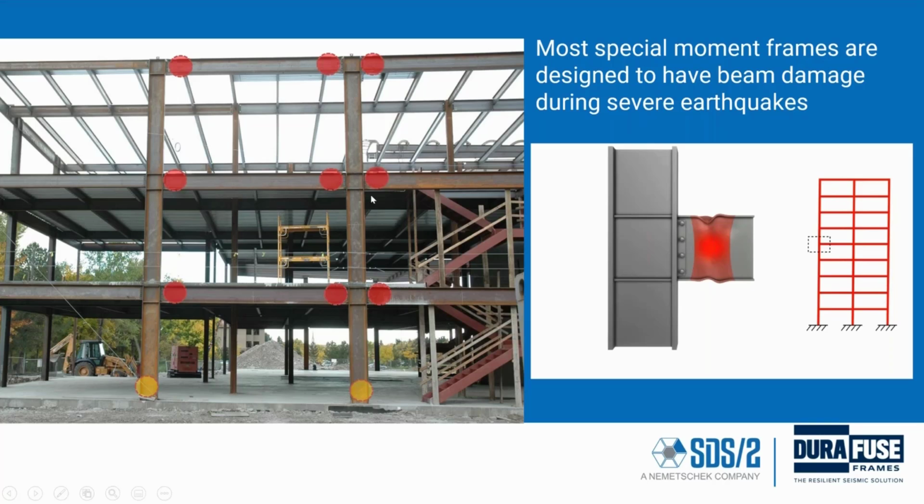Here's an example of a moment frame building. And when I say moment frame, I'm talking about frames that don't have braces in them. Here's an example moment frame, and these red zones are the zones that engineers have designed to yield and dissipate earthquake energy.